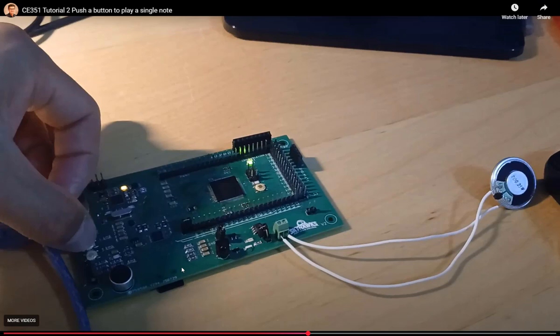So you can imagine there will be a while loop, right? While it is low, and then a curly bracket having that keep playing within the loop. So with a certain frequency, but how can you control that frequency? That's the question, because it's playing with a certain tone or pitch based on the frequency. You can use a time delay, delay it by a certain amount of time, and then toggle.